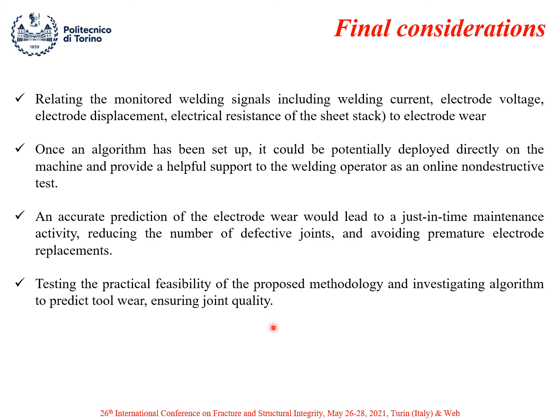So to make some final consideration, we have performed a study in which we want to correlate electrode wear with the quality of spot welds. And particularly, this correlation can be made by analyzing the welding signals and how they modify during the process according with the tool wear.